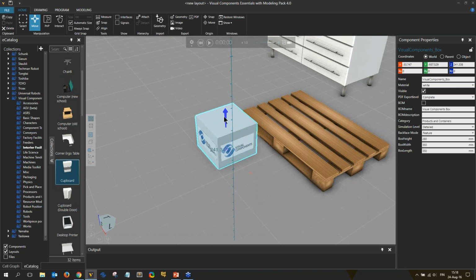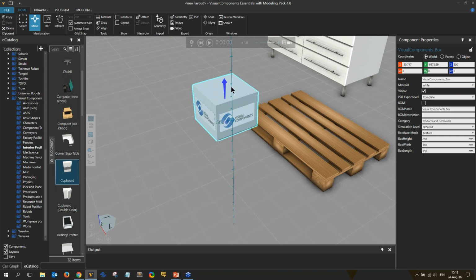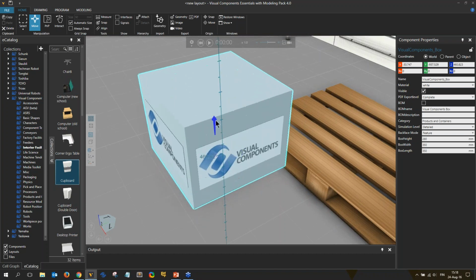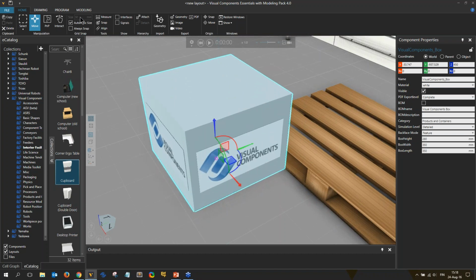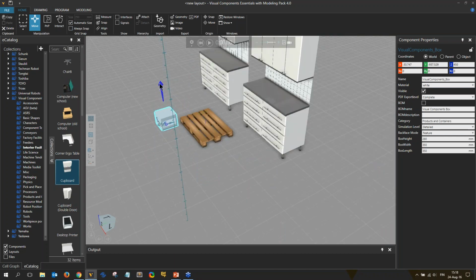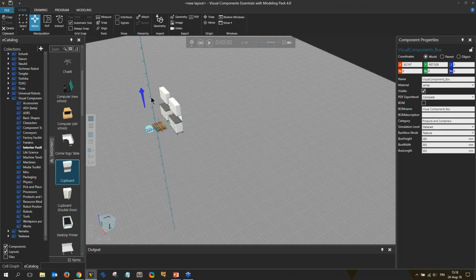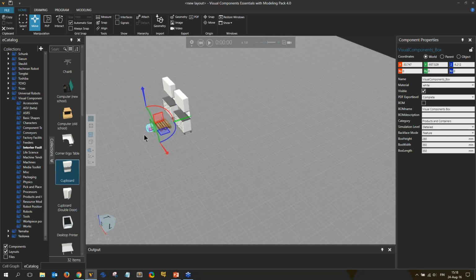And when you're doing this translation, you can again freely move along that axis, but you can also snap to these predefined measurements. And that grid scale is changing as you zoom in and out. You can quickly see it here. You can also force that to be always, for example, 50. But this automatic size here means that as you zoom out, this is now 250 millimeters. I zoom more out. Now it seems to be 1 meter steps. So that's a handy little feature there.